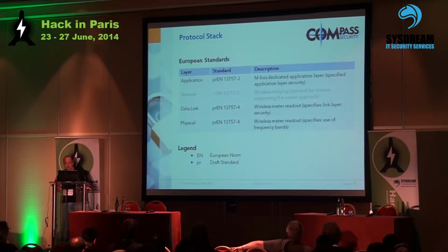When we look at the protocol among Europe, we mainly see them talking about 868 megahertz. There are actually also some devices which are using 169 megahertz, and with 169 megahertz you can make up to 5 miles line of sight.